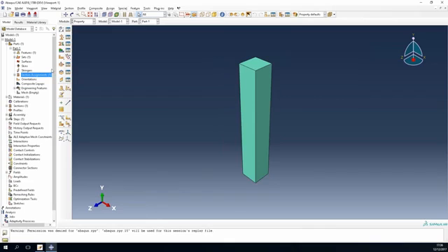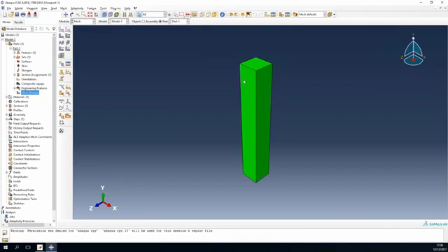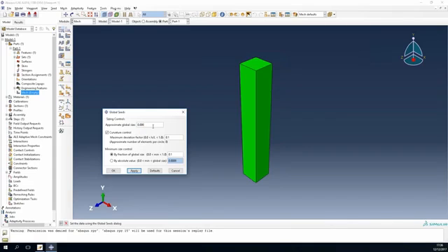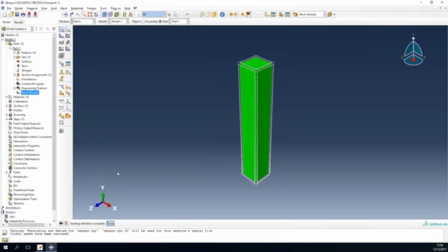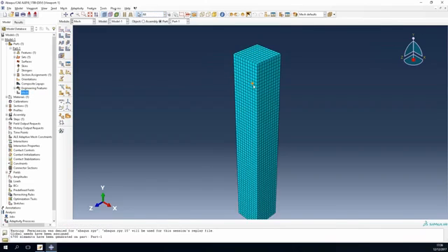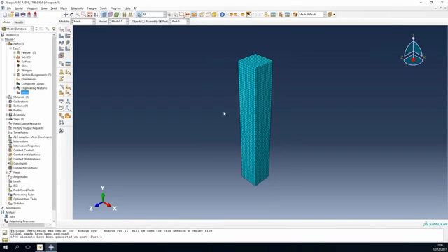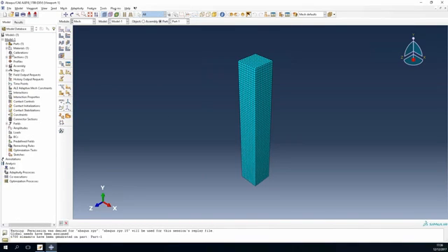So now we're quickly setting an explicit simulation in Abaqus, dynamic simulation. Okay, and as you can see, while I'm just creating the bar, I'm gonna now mesh it, and then we'll export that and set that as geometry in XFlow, structural geometry in XFlow. Okay, so that's my seeding, and I wanna mesh this part. So now I have a nice meshed 3D bar, and we can move to the next step.